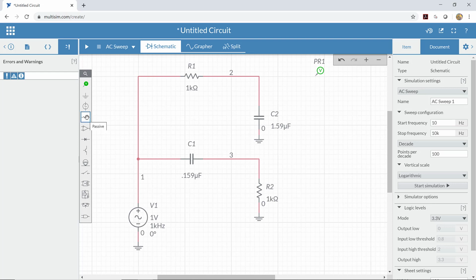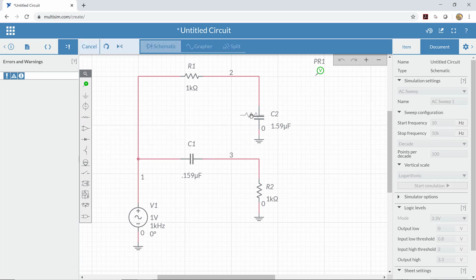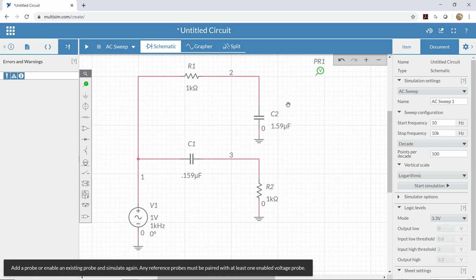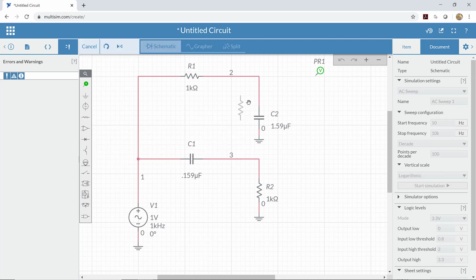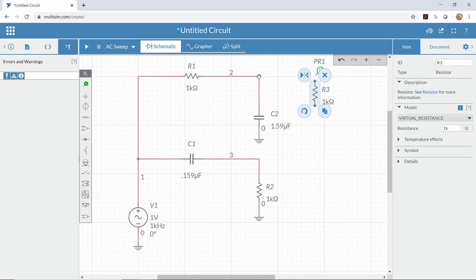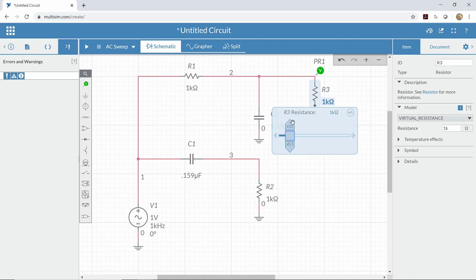So what we can do instead is put in some resistors, and these resistors allow the circuit to come to a compromise here. I'm going to use 10 kilo ohm resistors because that will not load down the circuit too much.